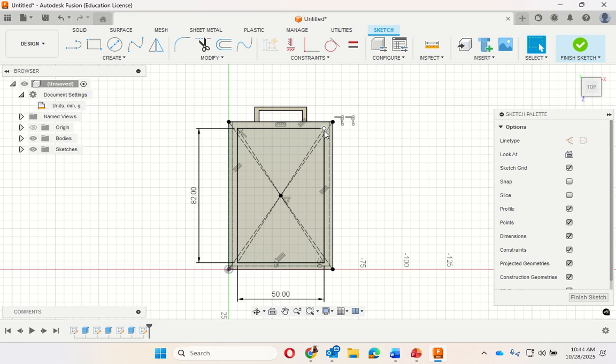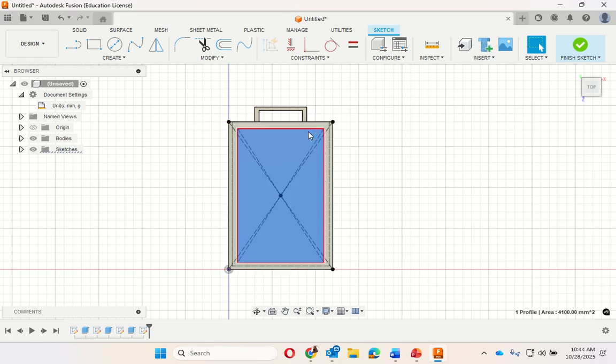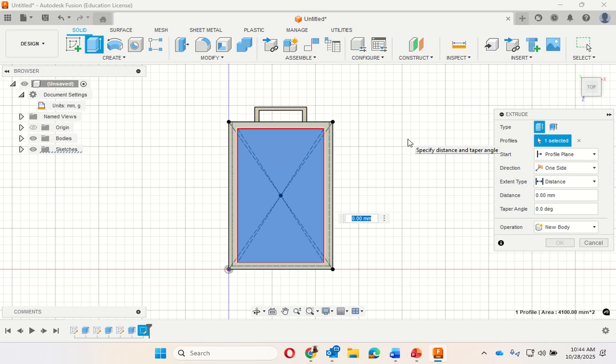So I have that lip to hold the picture, and now I'm going to take that rectangle that I just made, I'm going to press pull. It's the same as extrude, but the amount that I lifted it up was 2 millimeters. That rectangle right there, I'm going to go negative 2 millimeters. What do you think the negative 2 is going to do to that?